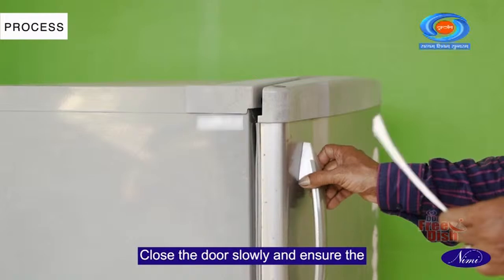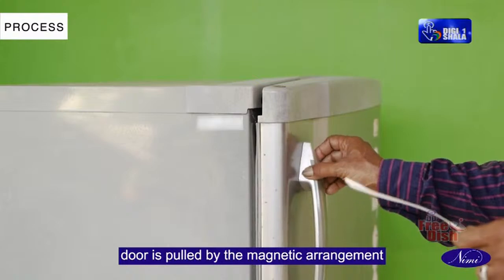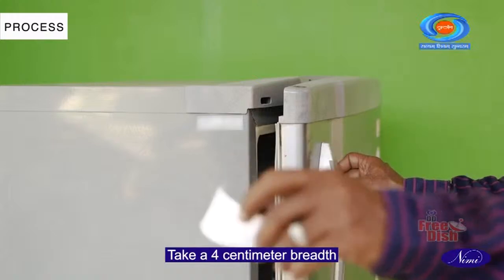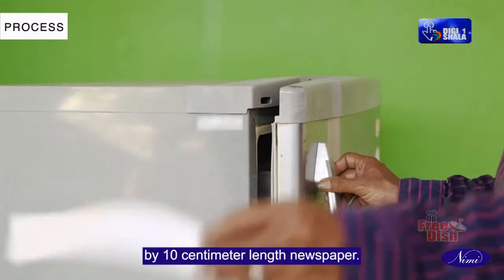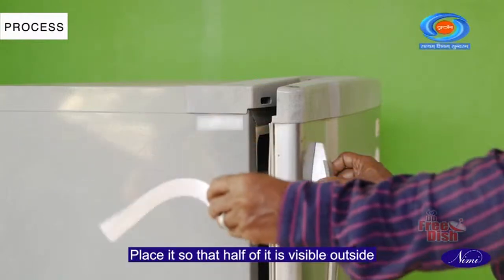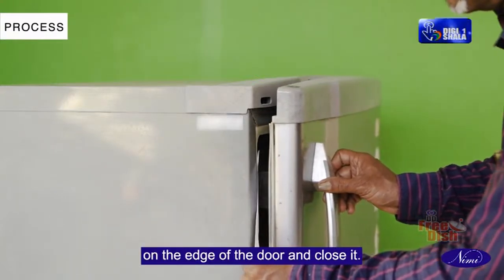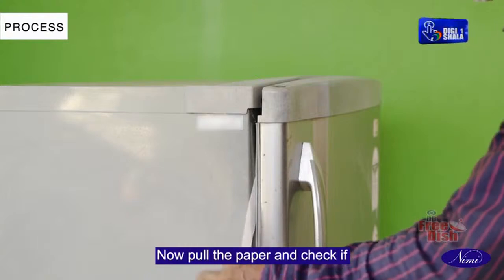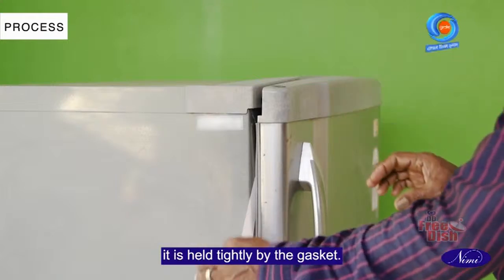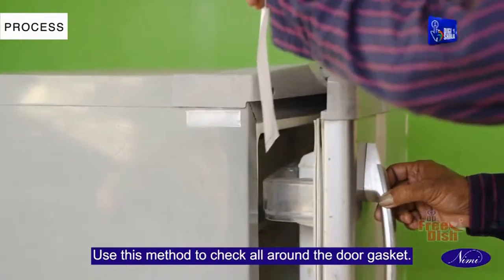Close the door slowly and ensure the door is pulled by the magnetic arrangement when it reaches the nearest closing point. Take a 4 cm by 10 centimeter length newspaper, place it so that half of it is visible outside on the edge of the door and close it. Now, pull the paper and check if it is held tightly by the gasket. Use this method to check all around the door gasket.